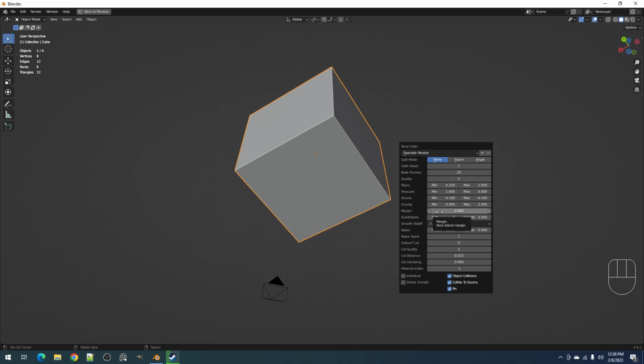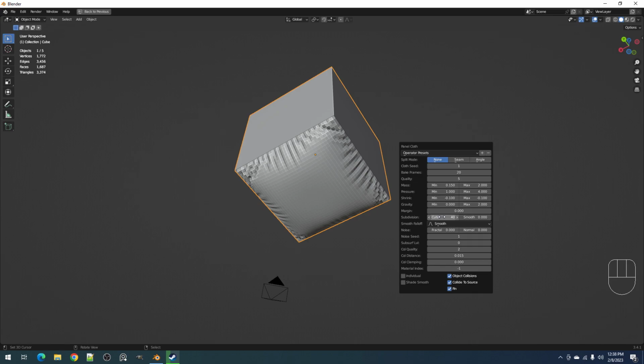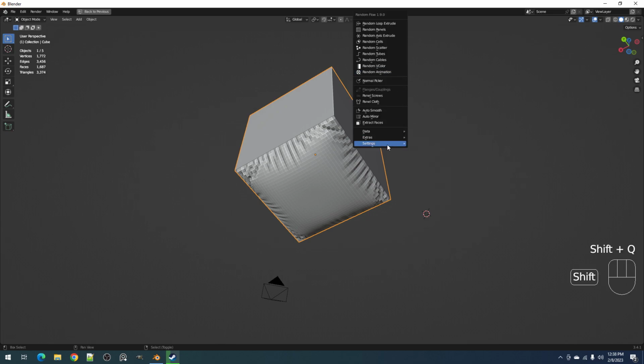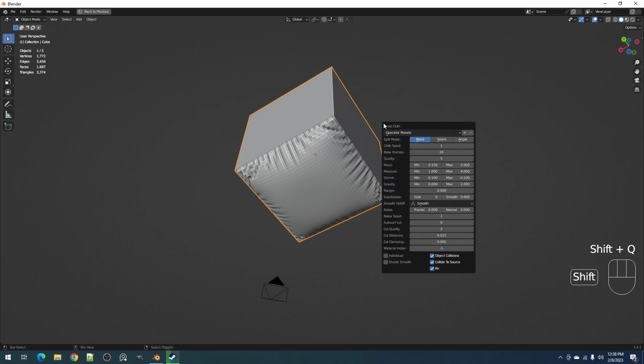If you accidentally used 16 subdivision for the single phase or 40, and you have a setting of 50 here and you selected something like 16 number of phases and then use the panel cloth, and this was not reset from the 40 value, then Blender will freeze. Okay? So just for extra security, it will revert back to 0 every time.